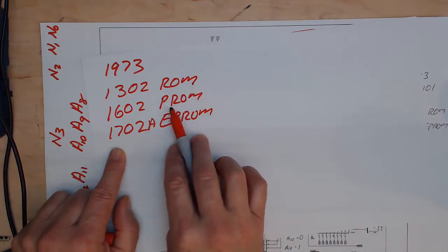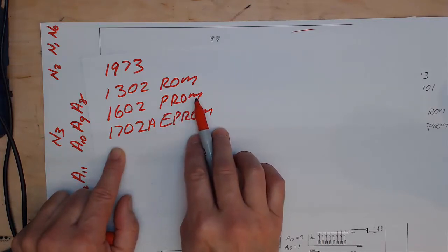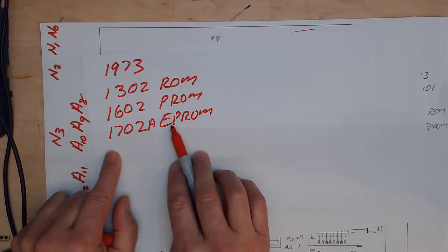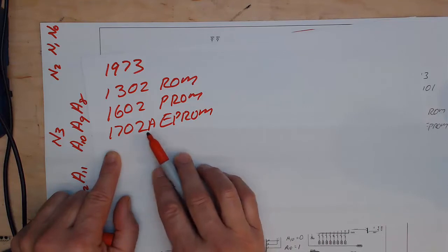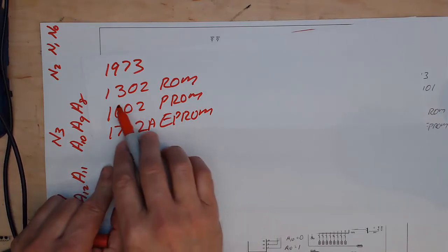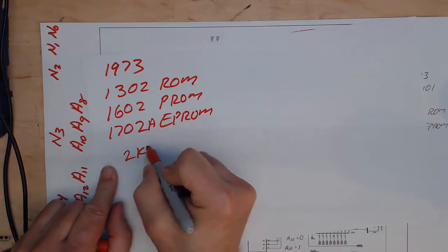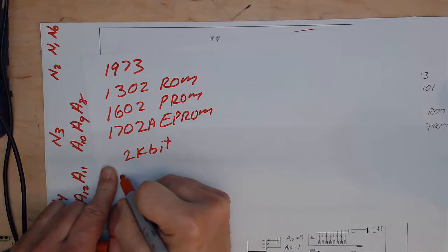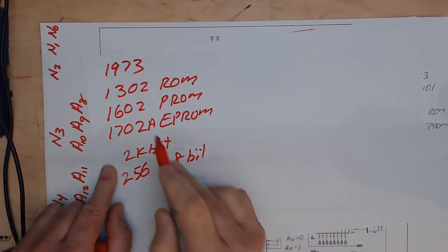The PROM, this meant that it was field programmable, but it was one-time programmable. So you would put it in a programmer and you would burn all the little fuses in each of the cells that you wanted, and that would give it its bit pattern. But of course you could only do that once. With the EPROM, we can shine a UV light on it, restore everything back because it has these isolated floating gates, and then we can program it again. So that's where we were. These were all 2 kilobit. That's what the 2 is for. So these were 2 kilobit, and they were set up as 256 lines by 8 bits. Okay, so that's what all of those were.